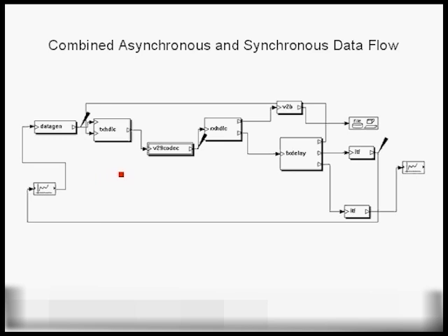In this case, the number of samples you generate depends on the noise in the channel. So here we're modeling an ARQ system with HDLC on the transmit side, HDLC on the receive side, and the data generator basically looks at a request to send in order to resend the packet in case of errors, and we also have an acknowledgement back in the case where we get correct packets.